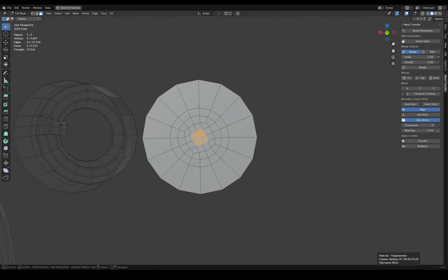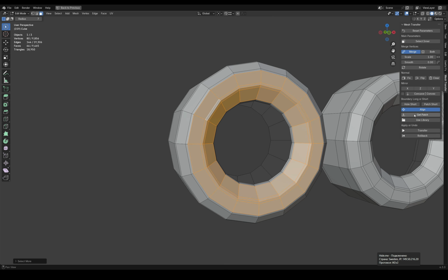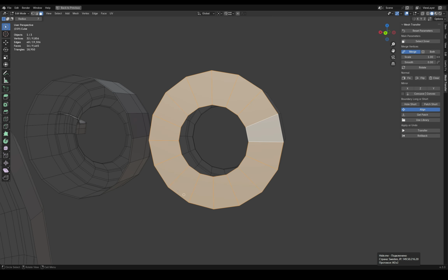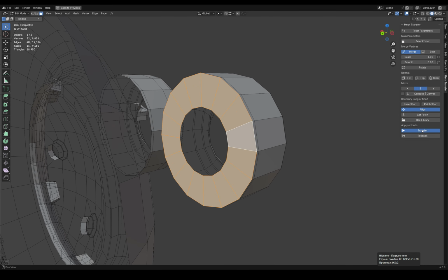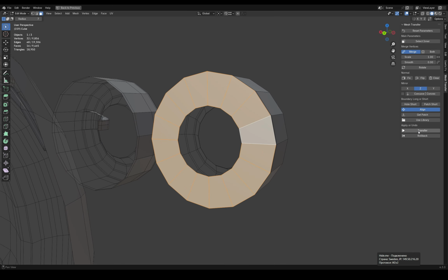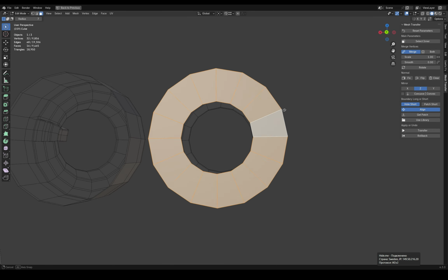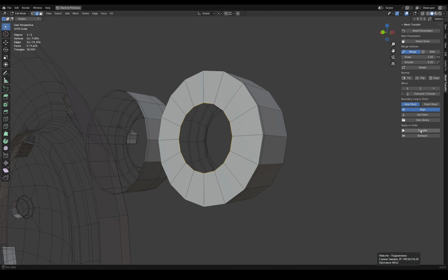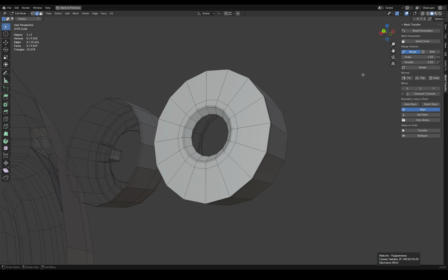I would also like to explain the hole short parameter to you. It works similarly to patch short, but for the main mesh where the patch will be inserted. If the parameter is inactive, the patch will be inserted into the longest border. If activated, then the patch will be inserted into the short border. In other words, this is a border switch, where we use either a long border or a short one. This is useful if we have a hole in the mesh or the patch.